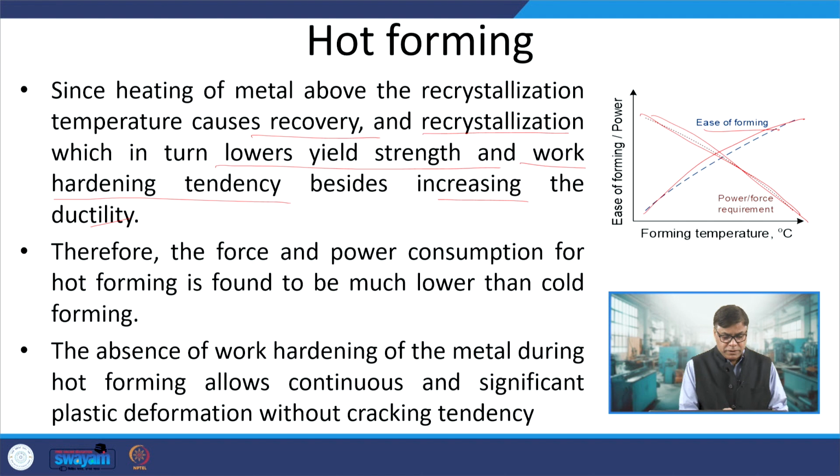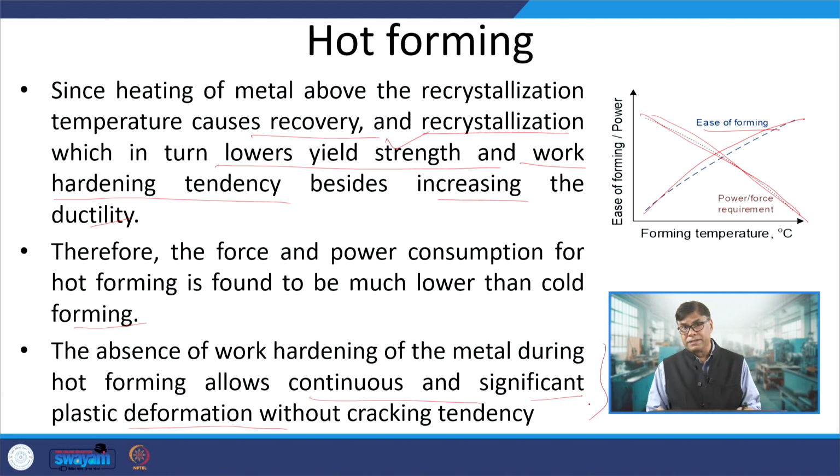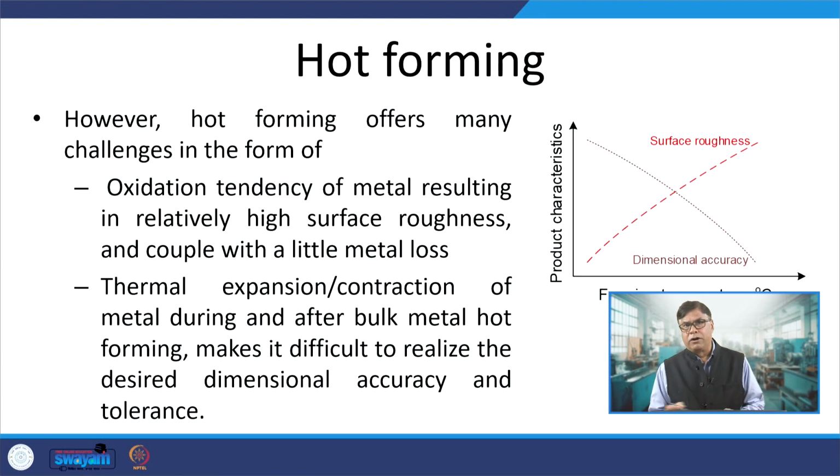Okay. So, the force and power consumption for hot forming is found to be much lower than cold forming, and this is particularly attributed to the drop in yield strength and a decrease in the work hardening tendency of the metal itself. So, the absence of work hardening of the metal during hot forming allows continuous and significant plastic deformation without the cracking tendency. So, this is the good part of hot forming, but there are many challenges also in hot forming.